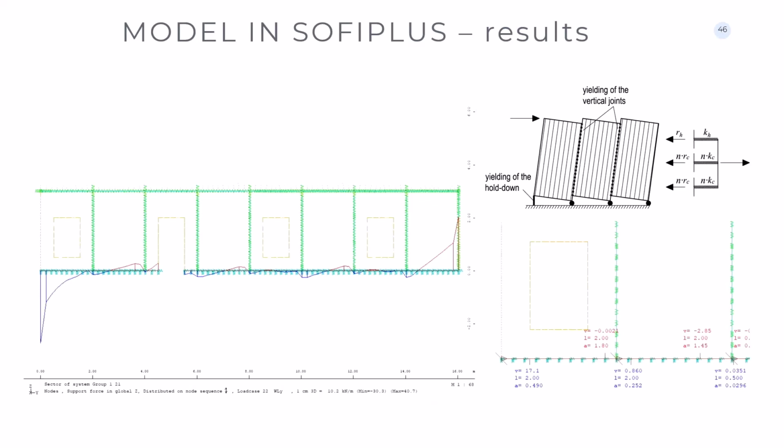And the other fantastic output we are using now, we don't know how to standardize that, but we are using it a lot, is that in reality, what you will do in the final phases is that you have, for example, tension forces here and compression forces here, and you will place two types of different connection. One is called the hold down. It's like a steel bracket that is very high here and connected to the concrete, and a small one here for shear and compression. And you want to know what is the force that they have to take.